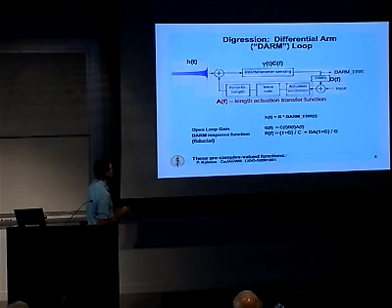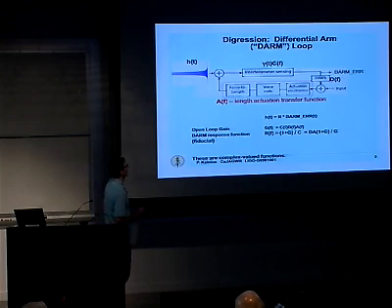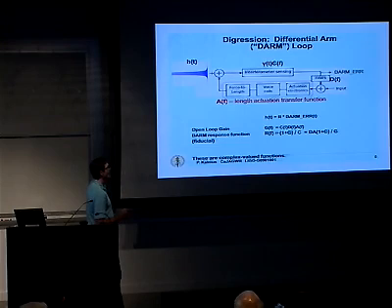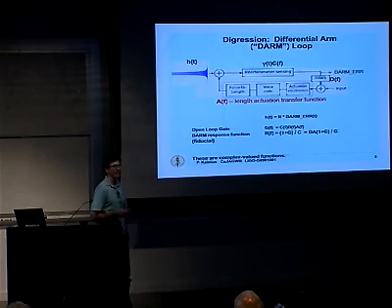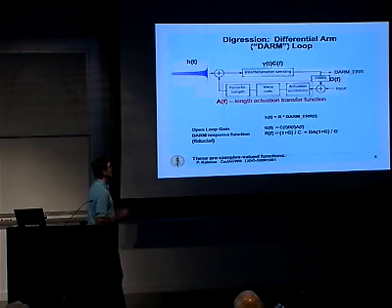A gravitational wave is sensed by the interferometer. The C of f is the frequency-dependent sensing function of the interferometer. The sensing function changes as a function of time as your optics change alignment, and maybe as your laser power changes. Then that produces the error signal from the photodetector, which is then sent through digital filters and is used to feedback on the coils. Okay, so that's the loop. And those are the three main functions: your sensing function, your digital filter function, and your actuation function.